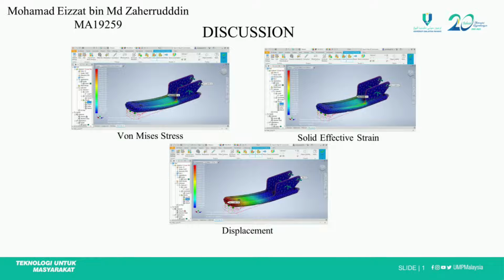Above that point, the deformation becomes plastic rather than elastic, and there is an irreversible component to the deformation. Lastly, the separation of an object induced by stress is known as a rupture or fracture. As the material thins, more pressure is applied until it snaps at the rupture stress point.